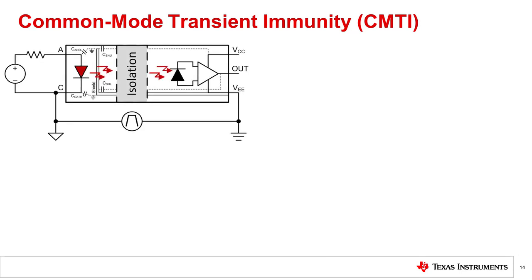Optoisolators have internal shielding that routes transients away from critical internal circuitry, but this shielding creates capacitances that can inject common mode currents into the driving LED. Most of the challenges in minimizing these capacitances are mechanical, and well-designed packages are required to reach acceptable CMTI levels.